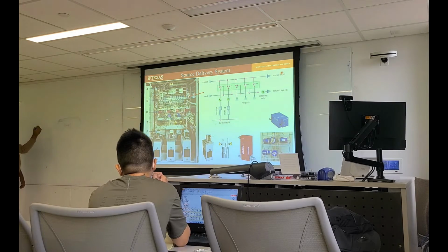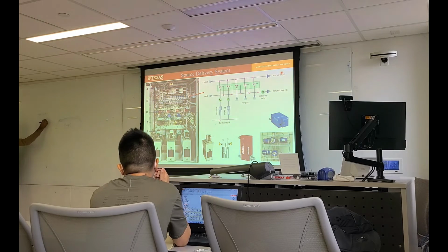You are using TMGa, trimethyl gallium, as the gallium source. Suppose for the thin film your flow is around 70 SCCM. But when you go to the quantum well growth, you need to reduce the gallium and introduce indium, that is InGaN in GaN.